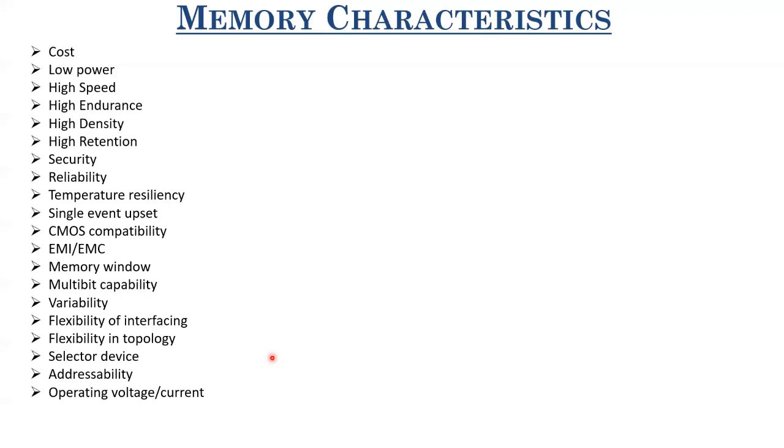Now the programming voltages typically in flash devices present nowadays is 20 volts. So with the 7 nanometer technology node, if you integrate a flash device, it won't be able to power it. So flash technology is an independent technology. So we need devices which can work within the voltage and energy constraints of the present technology nodes.